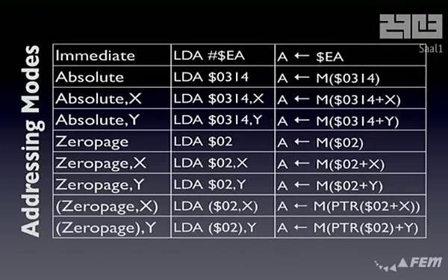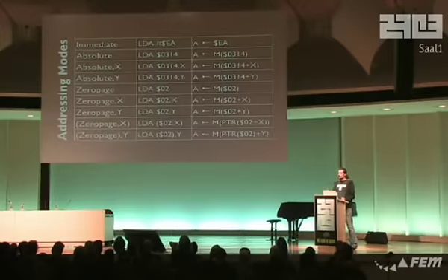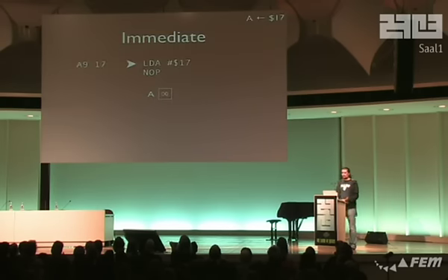So for all the general purpose instructions, these are the addressing modes that can be used in combination with these. There's an immediate addressing mode for using constants, absolute addressing modes, absolute and X and Y indexed. The same always with zero page, and then 2 special ones for special zero page stuff, which work around some other deficiencies of the design or some limitations of the design. Let's walk through the more important addressing modes for now.